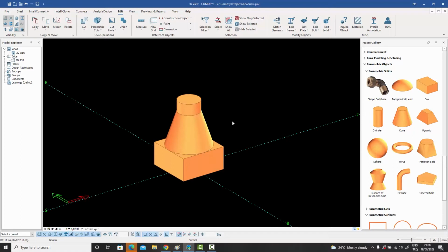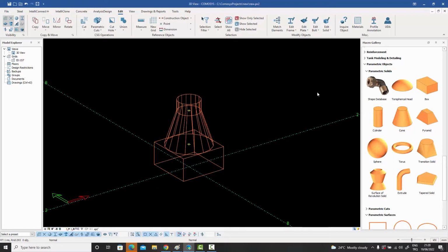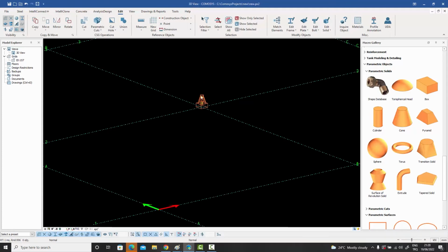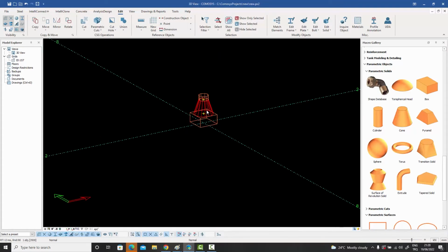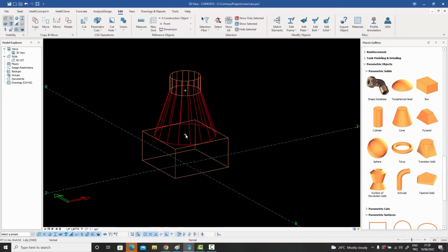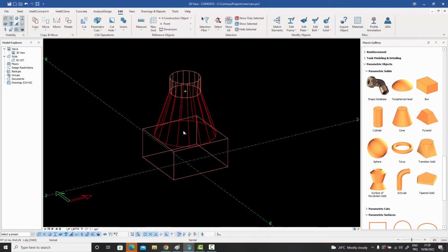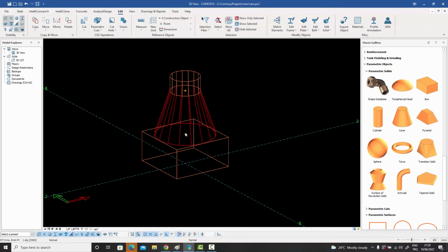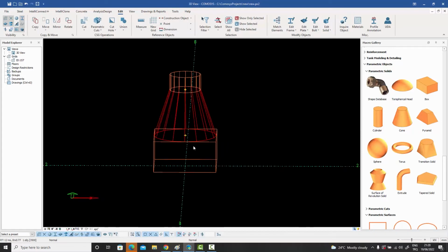one more thing you need to do as well is that before you enter the shape editor, you ensure that you have your origin. You can put your origin anywhere you want. So you have your origin points snappable. So I want my origin, this point to select, to this point to represent the origin, this point to represent my x-axis of this entire shape, and then a point over here to represent my y-axis.